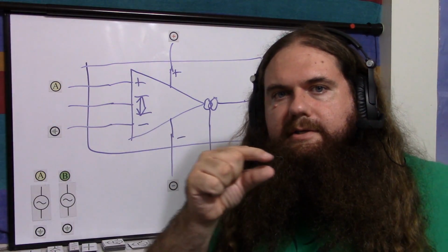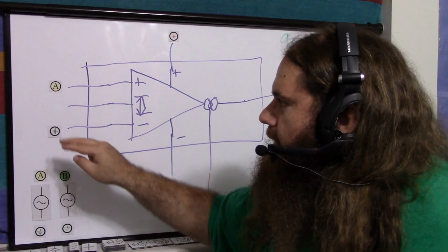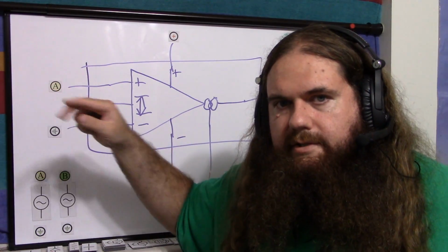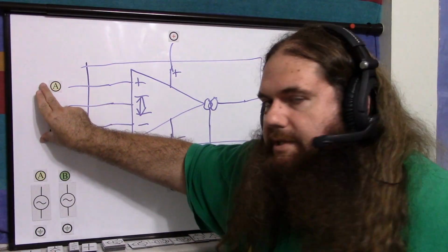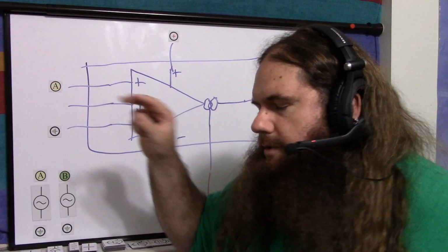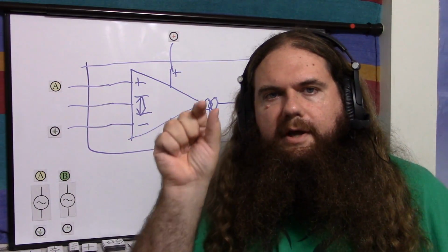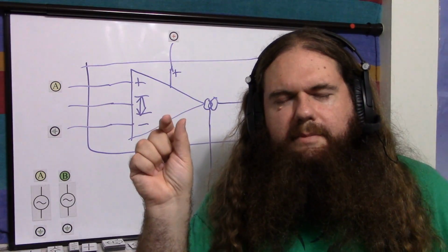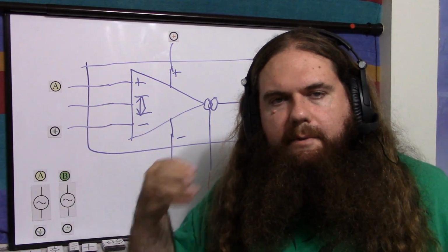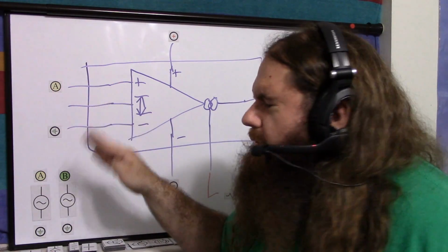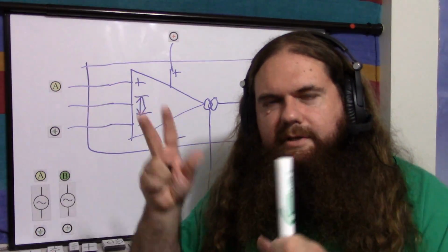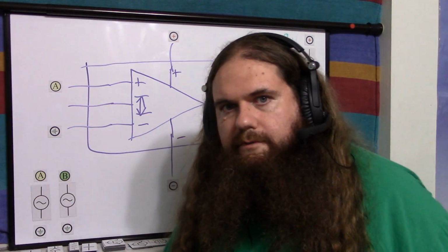So you're going to get a correct value. But the louder your signal gets, the higher the amplitude, the bigger this differential voltage. So the louder it gets, the more distorted it's going to get. So it's going to get too loud. And if you have high and mid and high and mid, and your waveform is wiggling, that might sound great normally, but if you don't have a linear response, then everything is going to get warbly. So that's why you use your voltage divider.